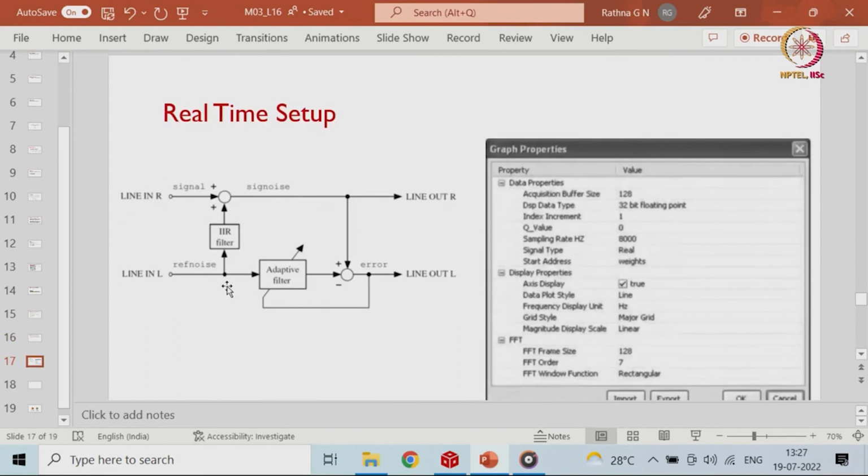So, this completes the adaptive filter part, for different applications, how we are going to run it using the board in real time. Whatever data, how system identification happened and how the noise is going to be cancelled, it can be non real time or real time, whatever you give. One more way of doing it is you can give the noise separately in one channel. Here it is mixed and then sent as an input to the system. One of them can be mic input, the other one can be line input, and then mix and match.